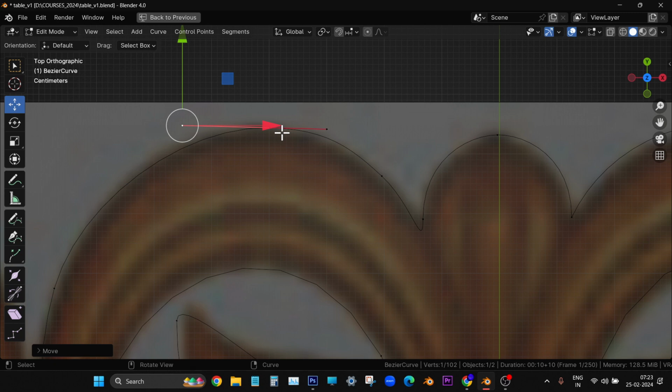So Bezier spline in 3D software is very important. Even for textures, we can make textures out of this Bezier spline. So we have to learn how to operate this tangent handle: make it big, scale it big, rotate it, and move it, all that.